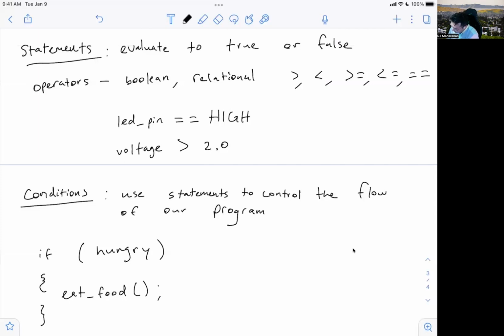Right, so then going back to Arduino language, maybe if button, or I guess so we read the button pin. So digital read, I'm just going to write dig read button. If we see a button press, then that's going to be high, assuming that we've got it configured like that.